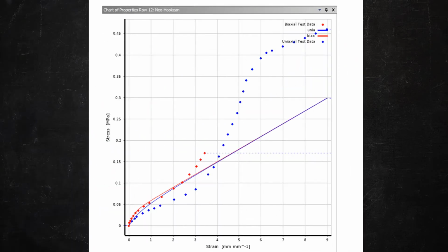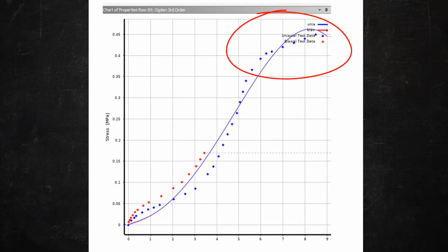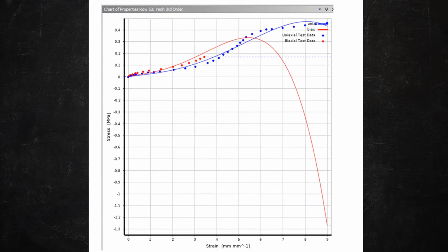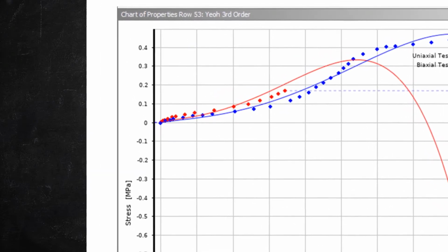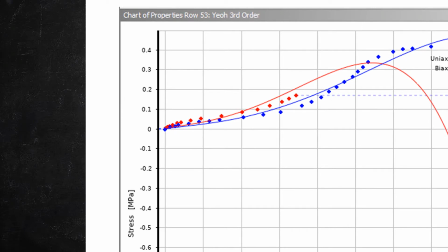We then run the curve fitter for different conventional options. Notice how the curve fit for Yeoh model seems to be okay for a lower strain range. However, for the higher strain range, the fit appears to break down. In this particular example, if the application were not going to be loaded into this higher strain range, perhaps we could accept one of these options.